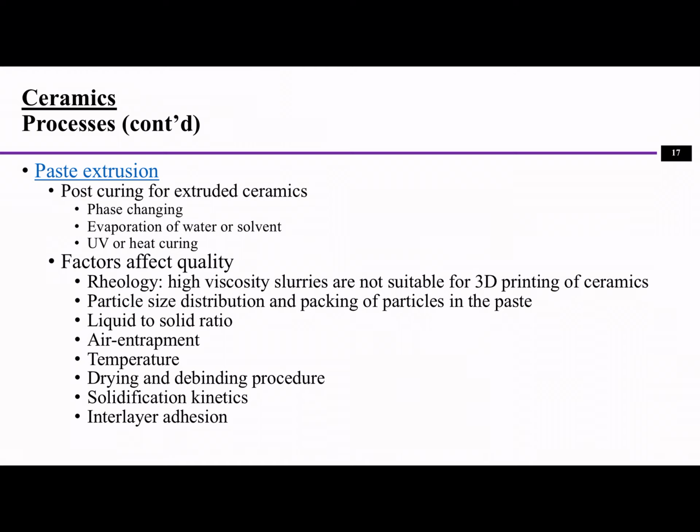But usually after that, a post-curing process is required, because the extrusion itself just creates the shape. Bonding of the particles in the structure also requires the sintering process. So that's why post-curing can be important. It changes the phase of the internal structure of the material, and it also gets all the water out. We can use either UV light or heat for the curing process.